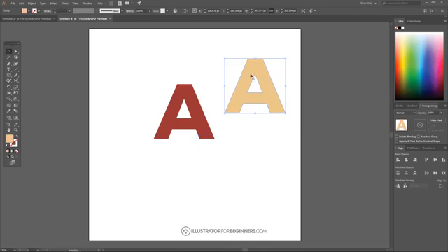And what I want to do now is give that an outline, otherwise known as a stroke. So to do that, let me click on the stroke color to make that active, and then I'll grab the Eyedropper tool, and then I'll hold Shift and click on that area where the color is that I want it to be. And it's going to give the stroke color that same shade. And then I'll go to this drop down for the stroke size, and I'll change that to 16.